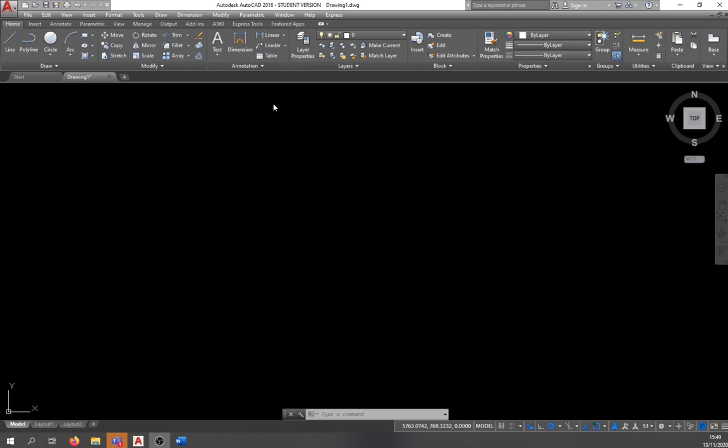So layers are different things. A door would have its own layer, furniture would have its own layer, walls would have their own layer. In theory, if you have a busy drawing, you could turn off all your door layers and all the doors would disappear. If you only wanted to show the mechanical, electrical and plumbing information, you could turn off all your other stuff and just show the plans for them. Or you could turn off all your concrete plans. So usually everything in AutoCAD is drawn on layers.